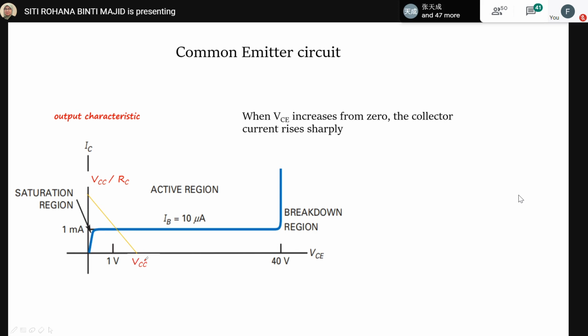But you have to make sure that the load line, I mean the line, and the intercept of the output characteristic, which is the blue line, and the yellow line, the load lines, do not overlap at the saturation region, because it's not possible for the BJT to operate in the saturation region, because both loops would be forward bias. Okay, both loops will be forward bias.